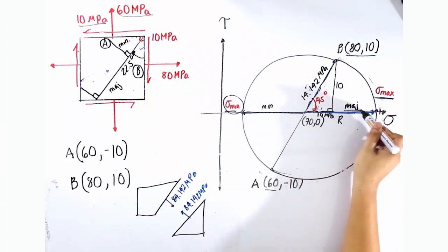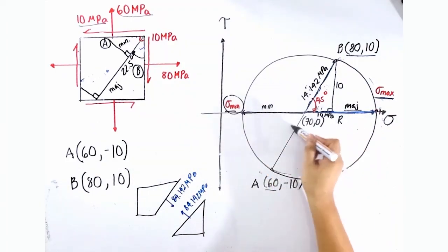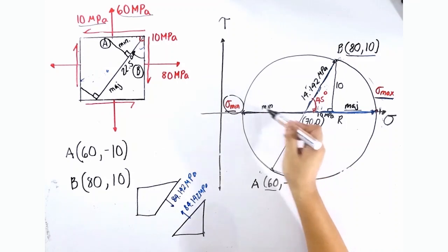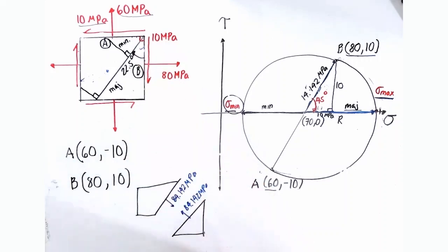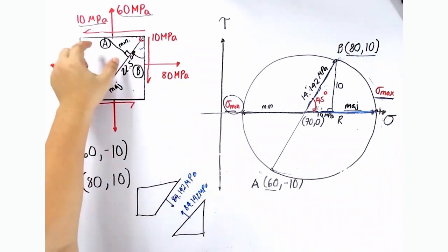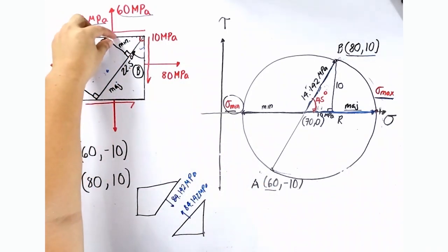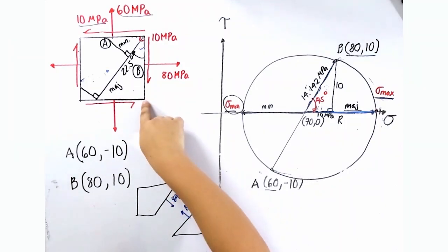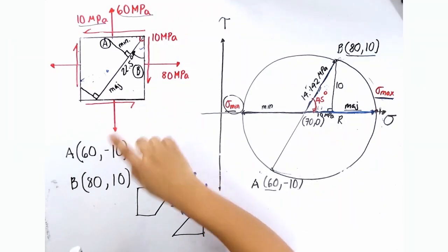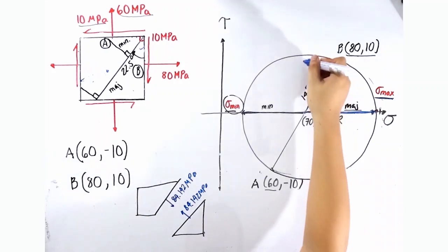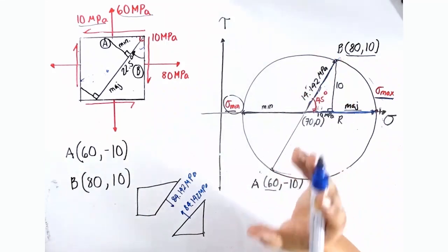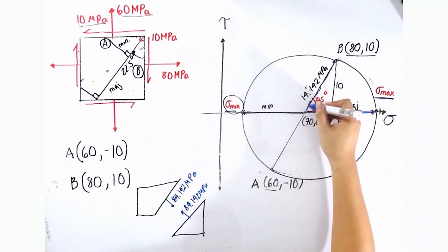So like this is major and this is minor. This is 180 degrees to each other. Therefore, if you're going to transfer it in our state of stress, it is perpendicular to each other. If this is 22.5, you can just get the orientation of this one geometrically. Determine the maximum shearing stress. If you are just considering the two-dimensional analysis of the Mohr circle, you are just getting the maximum in-plane shear stress. Look at the coordinate of the Mohr circle with the highest value of the y-ordinate.